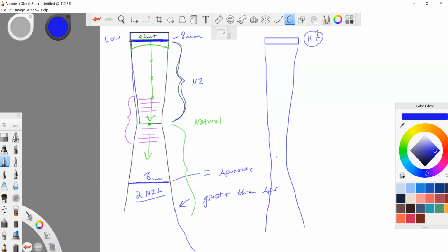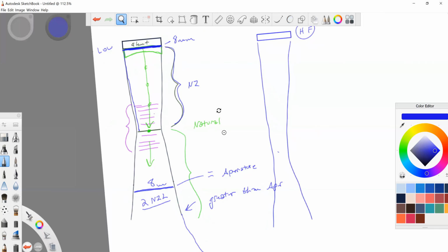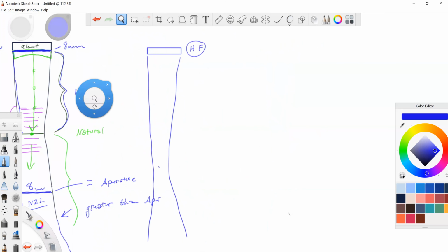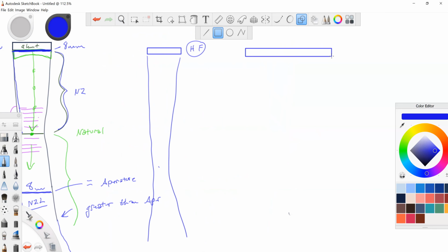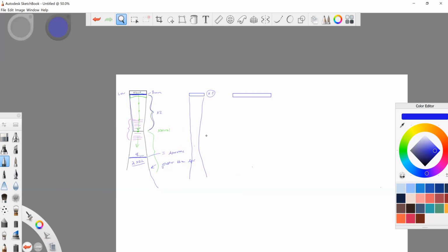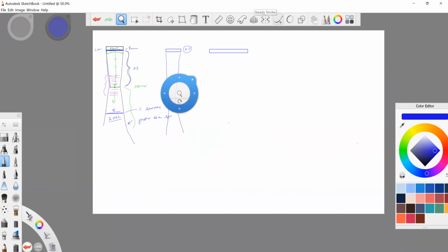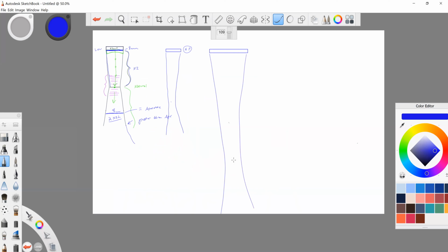The greater the diameter of the transducer's piezoelectric crystal, the longer the near zone length. That is true. Now that makes physical sense. So if I'm going to make a wide diameter, I won't be able to fit that on the screen anymore. Oh dear. Okay, well anyway, my focus is now going to be more like down here, with a very wide diameter. Let's say wide diameter and high frequency, so that was very low.